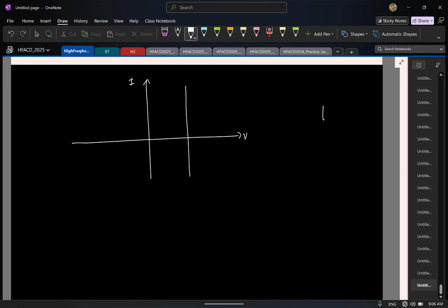Okay, let's say this is some device. The typical convention we follow is if the current is in this polarity, we define the voltage in this polarity. And passive devices generate power or dissipate power? Dissipate power. What is the power dissipated in this device? V times I. So if this were a passive device, what can you say about this power? Greater than 0 or less than 0? Power dissipated is positive, so it's greater than 0.